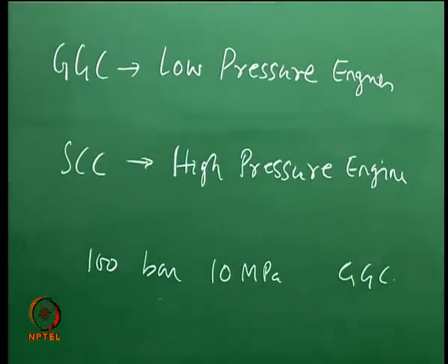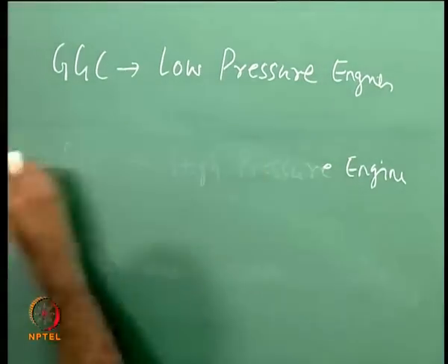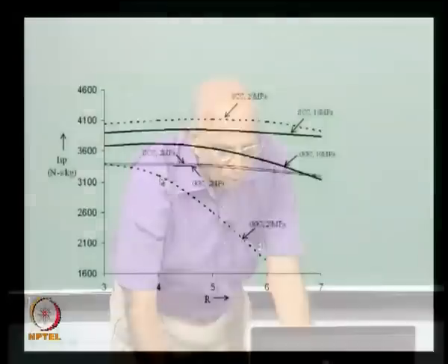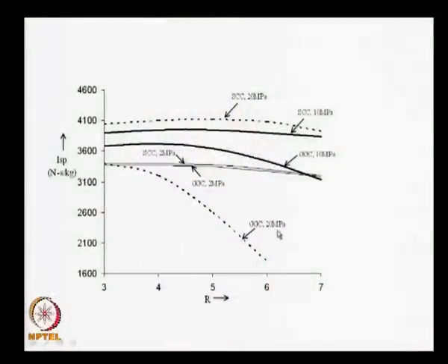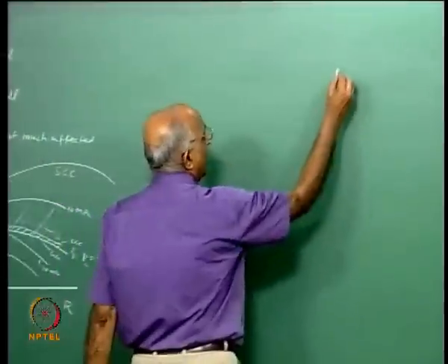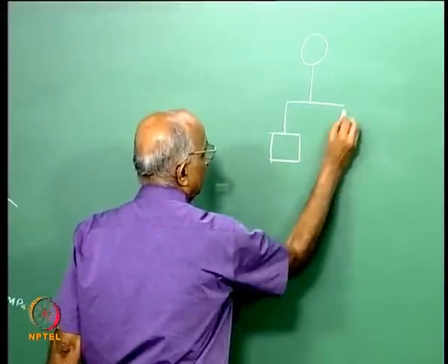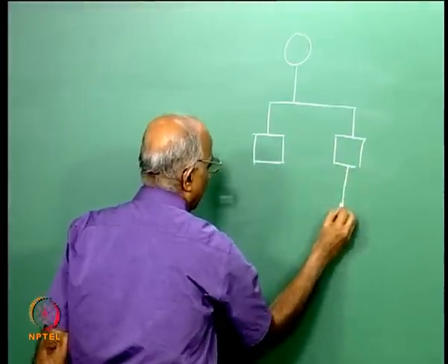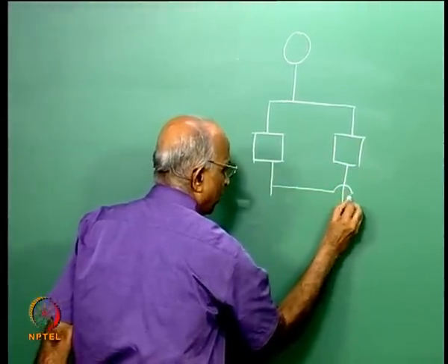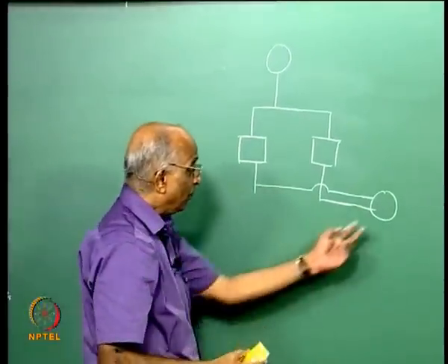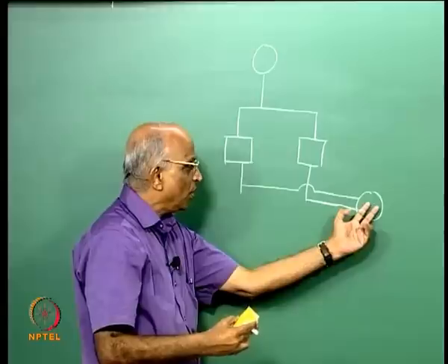To be able to complete the cycle analysis, I must also tell you why it fell down. The question is, why did the performance of the gas generator cycle fall so rapidly at higher pressures? It falls because when I have more of the fuel rich propellants, like for instance, I had a gas bottle, from the gas bottle I had the tanks, from the tanks what did we do? We took a little bit of the oxidizer, a little bit of the fuel into the gas generator, and this is, mind you, very fuel rich, and therefore I am bleeding more and more of it.